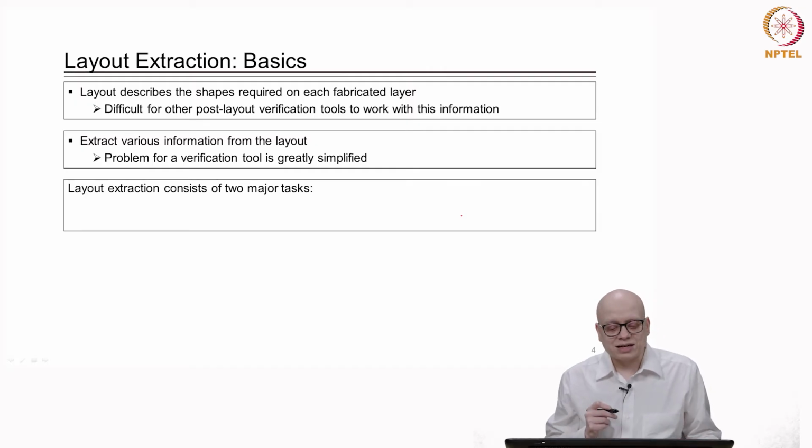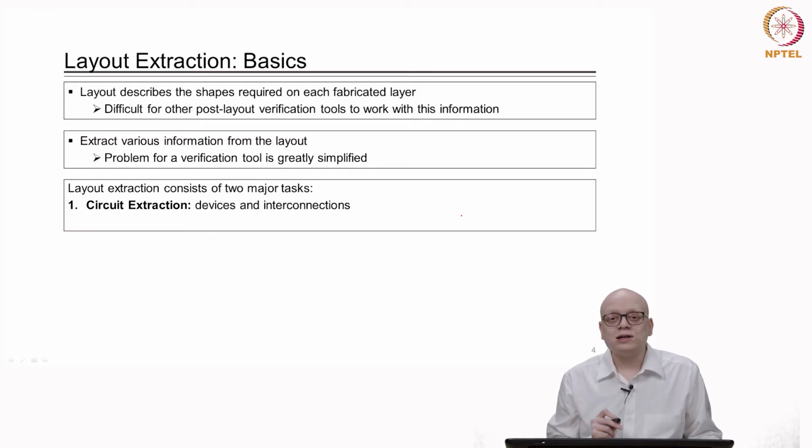Now, layout extraction consists of two major tasks. The first is circuit extraction, where devices and interconnections are extracted from the layout.